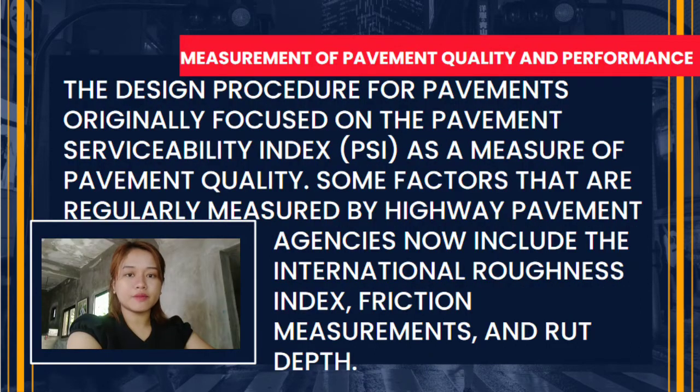Good day everyone, I am Sheenah Telan and I will now discuss to you the measurement of pavement quality and performance. So the design procedure for pavements originally focused on the Pavement Serviceability Index or PSI as a measure of pavement quality. However, the Pavement Serviceability Index is based on the opinions of a panel of experts, which can introduce some variability into their determination. Since there are different experts, opinions will also be different, kaya magkakaroon ng variation.